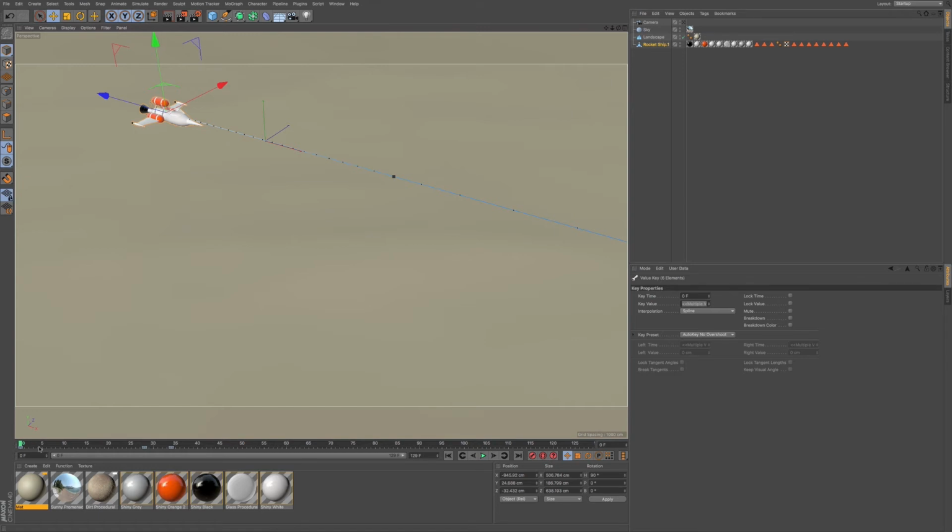So it's a pretty good option if you want to move a whole amount of keyframes down your timeline. For an example, say you realize that you don't want your jet to start taking off right when the movie plays. So when you first play, the jet takes off. But what if you wanted to have a bit of a pause? So what you can do is click and drag all these keyframes by clicking this keyframe, going to ripple edit and clicking on this keyframe, and now you can move all the work that you did.